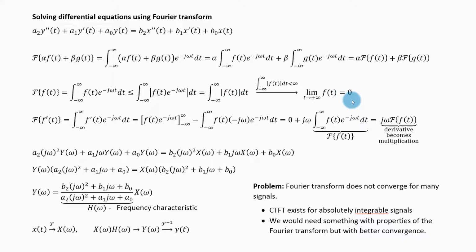You may recall though that we worked with the Fourier transform of signals that do not satisfy this condition. For example, we worked with the Fourier transform of a sine or a cosine. But with these functions, I was actually cheating a little bit. To express the Fourier transform of a cosine, we had to use Dirac delta pulses, which are actually not functions. They are so-called generalized functions or distributions. And you may also recall that I have never actually evaluated this integral for sine or a cosine.